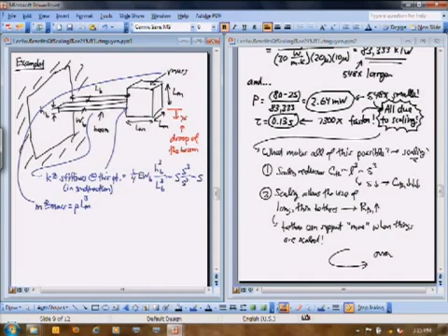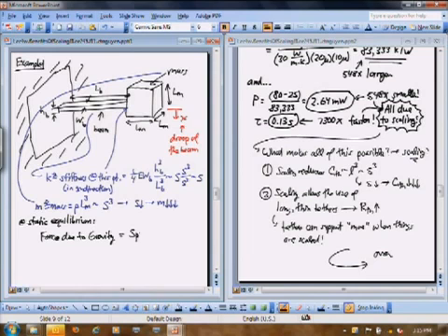So at static equilibrium, I'm going to have a force acting on the mass due to gravity, and that's going to be equal to the restoring force applied by the spring. So in the end, I'm going to have something like this. I have this force here, which is going to be mass times acceleration, where g is the acceleration due to gravity. And that's going to be equated to what the spring is exerting on this, which is kx in the upward direction. So I can just write mg equals k times x.